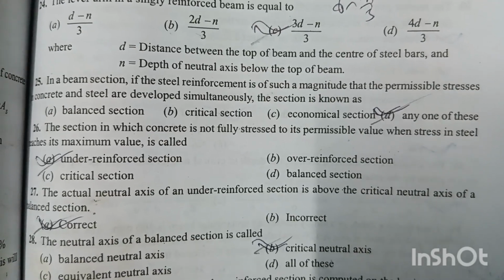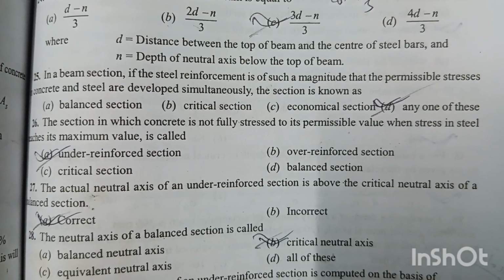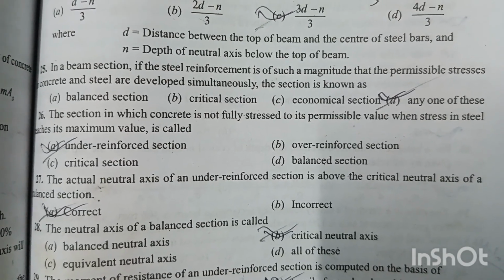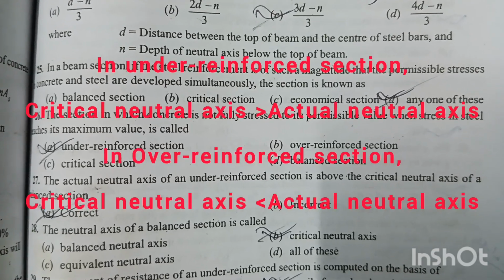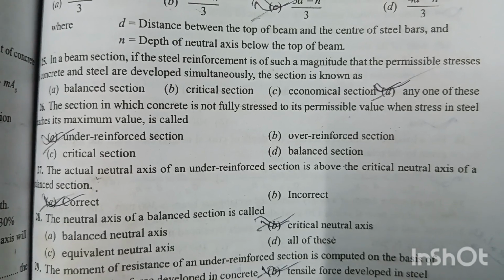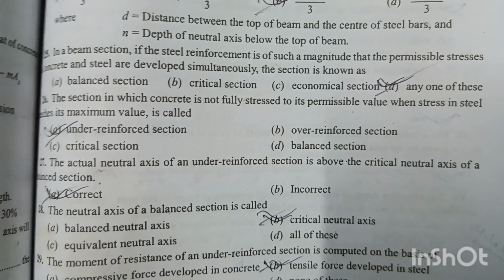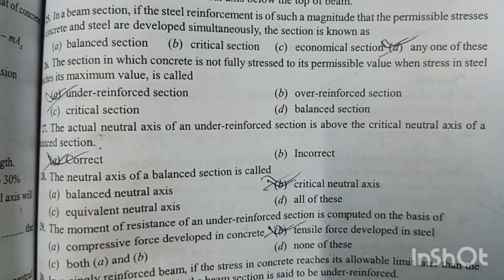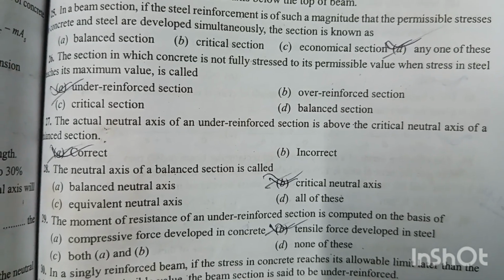Question number 26. The section in which concrete is not fully stressed to its permissible value, when the stresses in steel reaches its maximum value, then it is called under reinforced section. Option A is right answer. Question number 27. The actual neutral axis of an under reinforced section is above the critical neutral axis of a balance section. Option A is right answer, correct. Question number 28. The neutral axis of a balance section is called critical neutral axis. Option B is right answer.